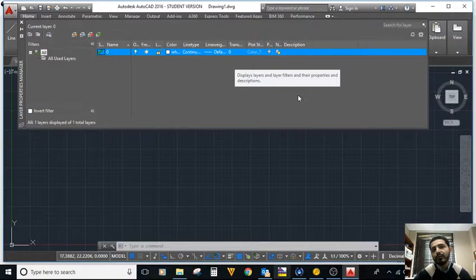One of the good things about this is you can deactivate one layer, you can hide one layer, you can show another layer, and every layer has its own properties. What does that mean? It means that if I have one layer that draws the external lines of the buildings, maybe it's thicker, with a different color, compared to the lines inside.